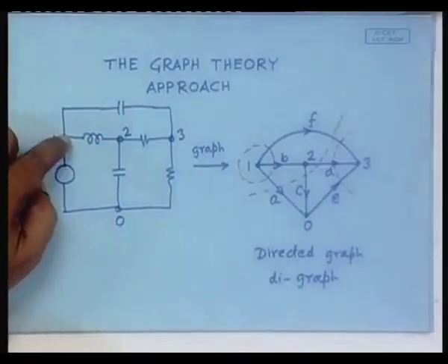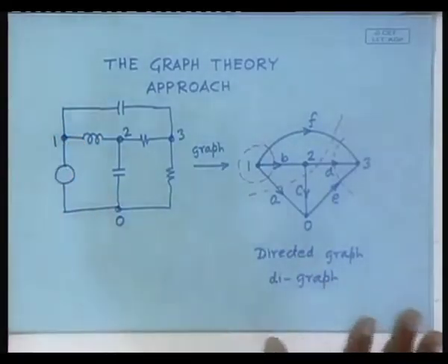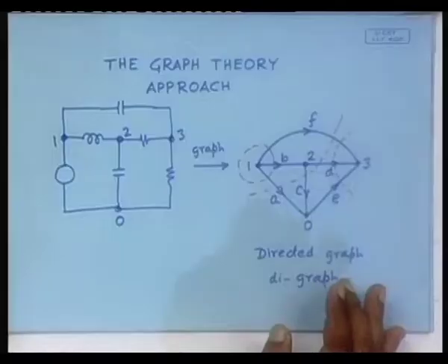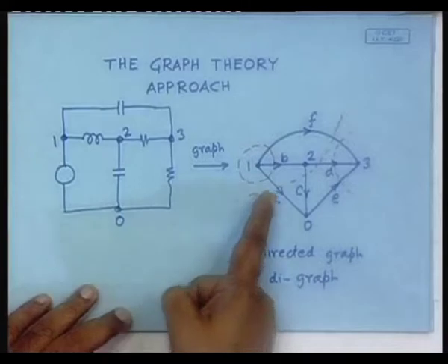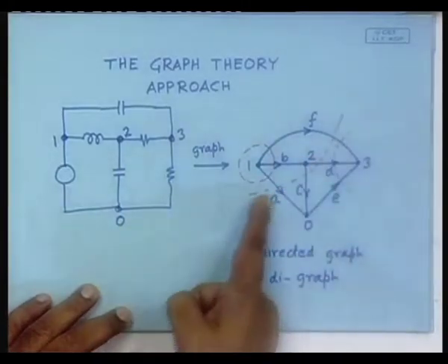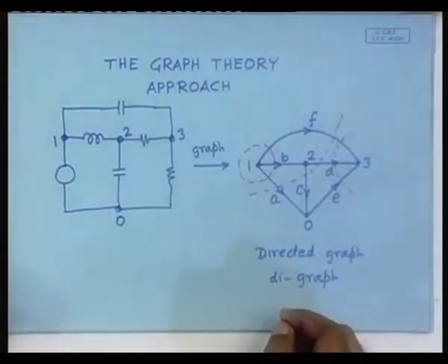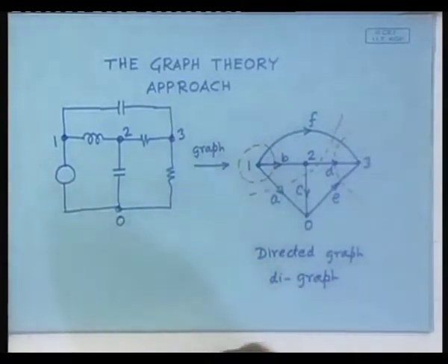Earlier when we wrote the Kirchhoff's current law, we said that in each node all the currents entering or exiting sum to 0, right. Now, we will restate it by saying that at any cut set, all the currents going from one side to the other, one subgraph to the other subgraph, sum to 0. So, it is a higher level of definition of the Kirchhoff's current law.